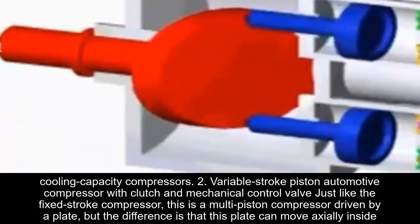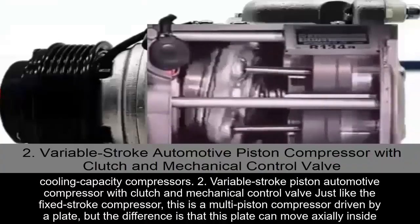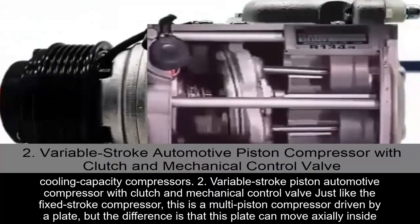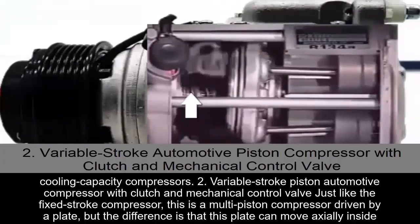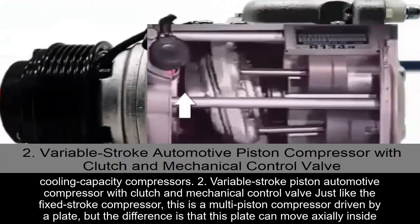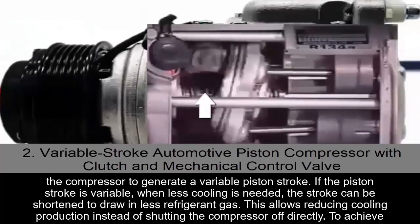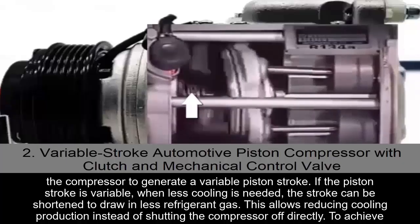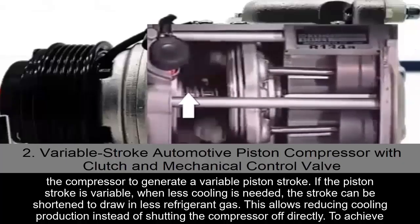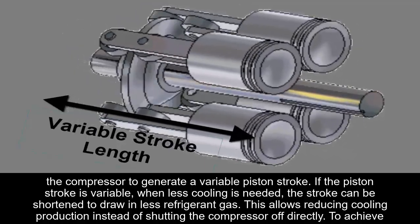2. Variable stroke piston compressor with clutch and mechanical control valve. Just like the fixed-stroke compressor, this is a multi-piston compressor driven by a plate, but the difference is that this plate can move axially inside the compressor to generate a variable piston stroke. If the piston stroke is variable, when less cooling is needed, the stroke can be shortened to draw in less refrigerant gas. This allows reducing cooling production instead of shutting the compressor off directly.